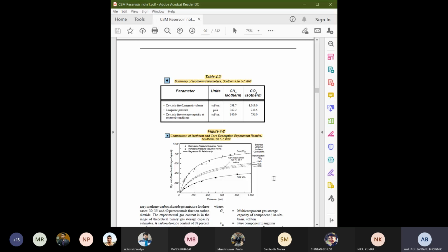So what will happen? The stage adsorption is the maximum at the first step, because the total accessible pore volume is available. Sometimes the maximum is also shown in the second step. Why? Because it will depend on how many particles you send at each pressure step and what the pressure of that pressure step is. Depending on that, your graph shape is also going to change. So you can see that the methane graph is going to be uniform, just flatter.